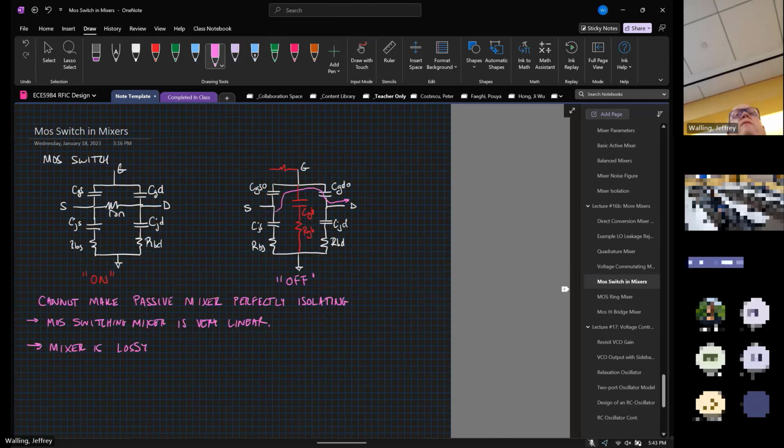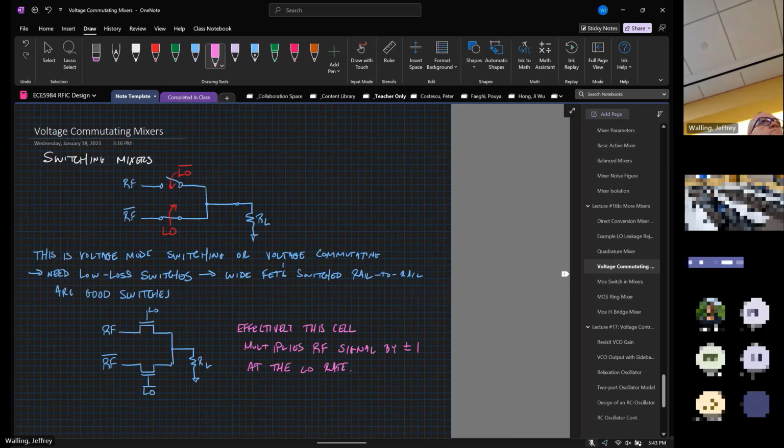Another question. Yeah. The switching mixers. In VLSI, they use like a transmission gate so that if the signal is very high or very low, it wouldn't turn off the transistor. Do they also do that here? Is that not necessarily just biased to RF?